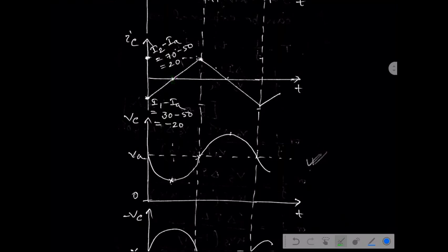That means the inductor current gradually decreases from its negative current of 30 ampere to 0. That means excess 20 ampere current is delivered from the capacitor, due to which in this particular region the capacitor is discharged and the capacitor voltage falls. Clear?